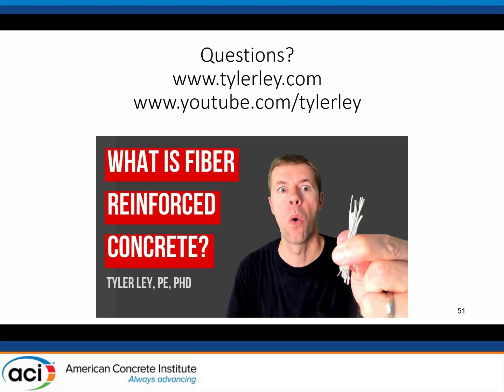I suppose we're supposed to use the microphone, but I currently have a project where we're trying to decide why there's a difference between the cylinder strengths and cores that we've cut through full-scale structural specimens. And so in hearing what you're saying, it sounds like these cylinders were cured in plastic sleeves, and they were supposedly kept wet, but we're not sure that they were. Were cured in plywood forms. So I guess the question is just, the plastic alone, sounds like from what you're saying in this presentation, the plastic is going to have an influence on the curability or the durability of the resulting cylinders?